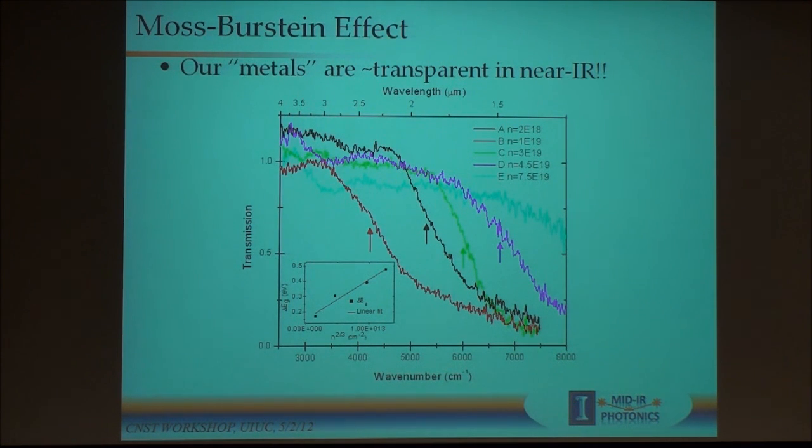But the other issue is actually indium arsenide, and this is some work done at Bell Labs, I think 30, 40 years ago. You can really dope it highly degeneratively n-type. And it has to do with this Fermi stabilization level that lies well inside the conduction band. But I think it's harder to dope this highly p-type. I think it gets trickier to dope p-type.